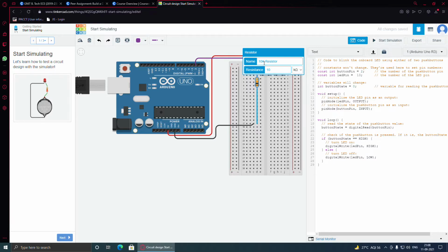If we are connecting an external, discrete resistance in series with the component, then we are adding the resistance of the external resistor to the internal resistance of that component. So the whole resistance is being taken into account. In that case, if the resistance is moderately high, say 5 kilo ohm or 10 kilo ohm, the voltage value of 5 volt is suitable. The current rating of a few milliamperes is maintained, as the resistance value is making up for the high voltage, which is 5 volt.